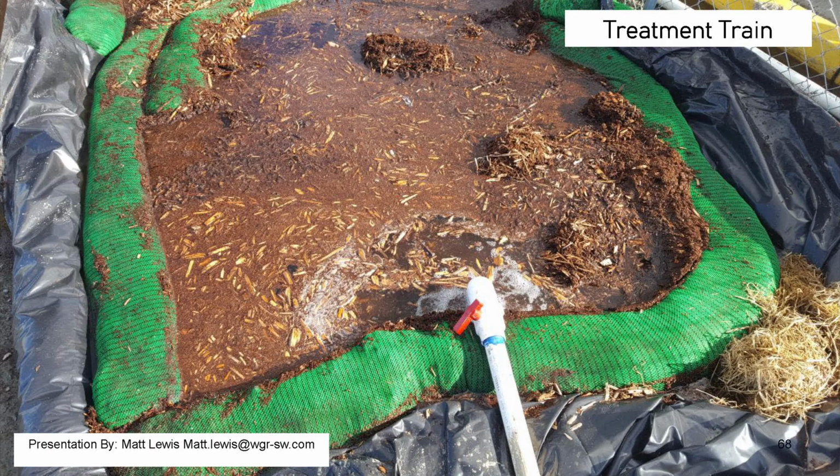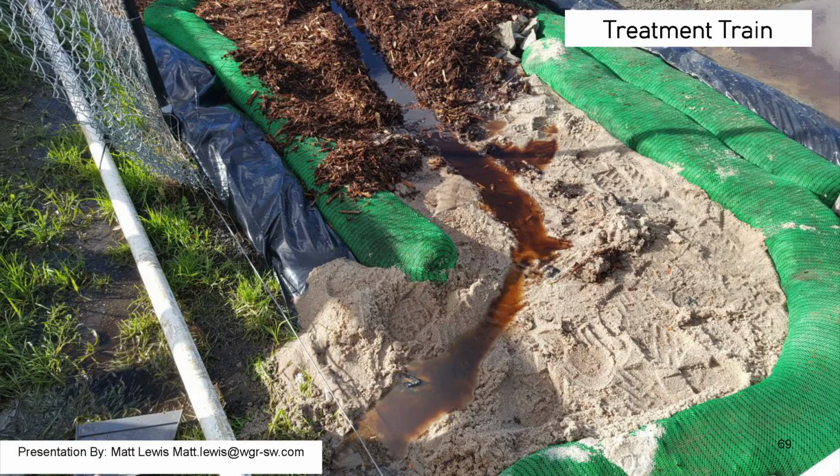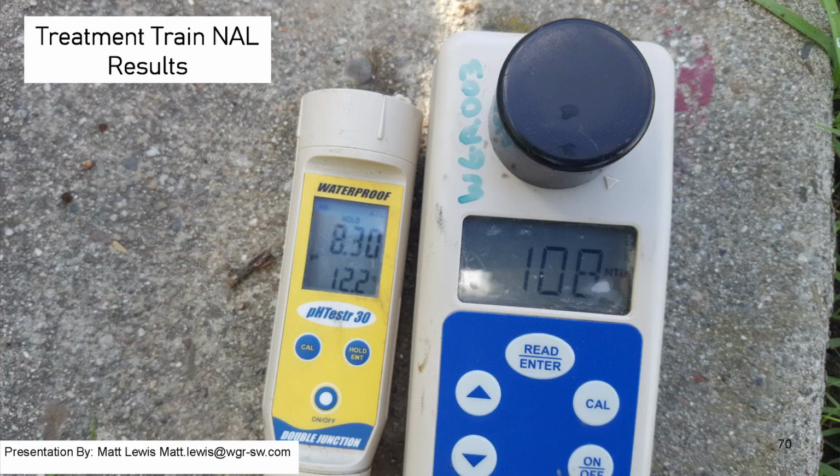Believe it or not, just flowing through, if I'm not mistaken, they were in the 400s for NTUs, and their pH was through the roof, in the 9s. Surprisingly, they go through 3 sections of mulch, and they're also going through 3 sections of compost sock, and it brought it down. This works almost every single time, and it's pretty cost-effective: a load of mulch and 10 or so compost socks and some sand, and you've got yourself some clean water.